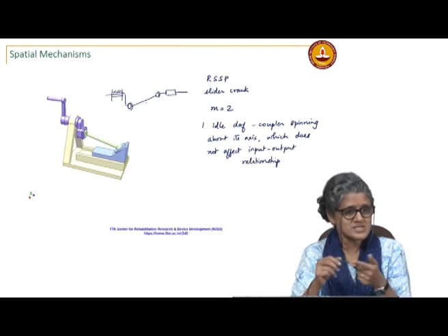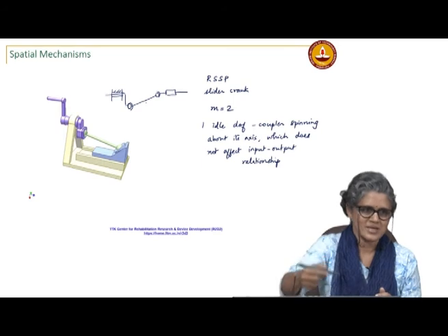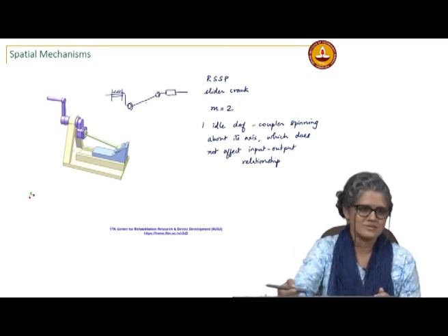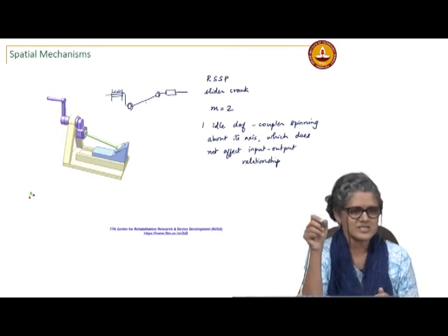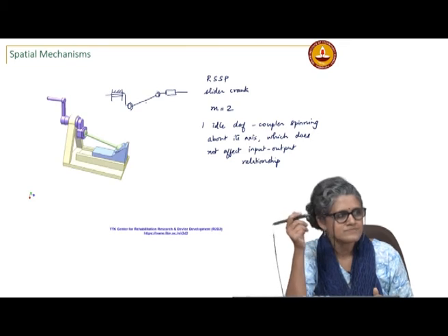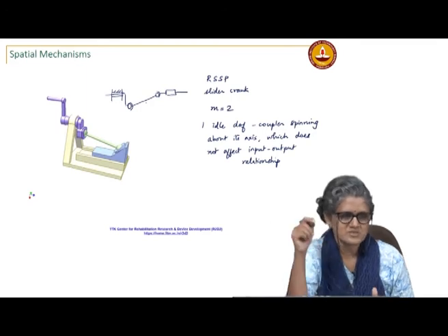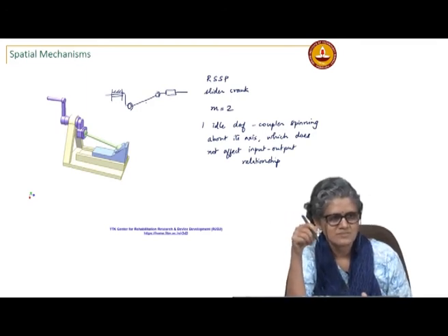That is the relationship between your input and output. When you are moving this in a cone, the vertex of the cone remains where it is. What would be the purpose of this mechanism? If you want to disengage a clutch or something, you can just shift it to the cone and the rotation will not move further. It will stop there because of the singularity. But I don't know if they use something like this; it would be too complicated. But the mobility still comes out as 2.